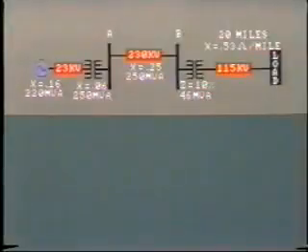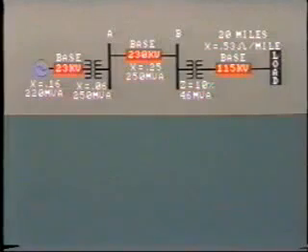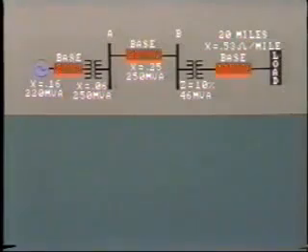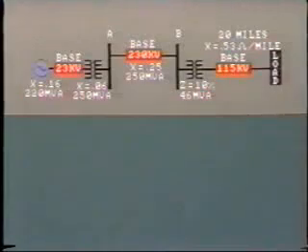So now that we've established the utility of the per unit system, let's look a little closer. Usually, base voltage and base voltamperes are chosen arbitrarily. And then base impedance and base current are derived from these. Base voltage should be chosen to be the nominal voltage in particular parts of a system. In our example, that would be 23 kV, 230 kV, and 115 kV base voltage for these specific areas. Clearly, we will have several different voltage bases on most power systems.